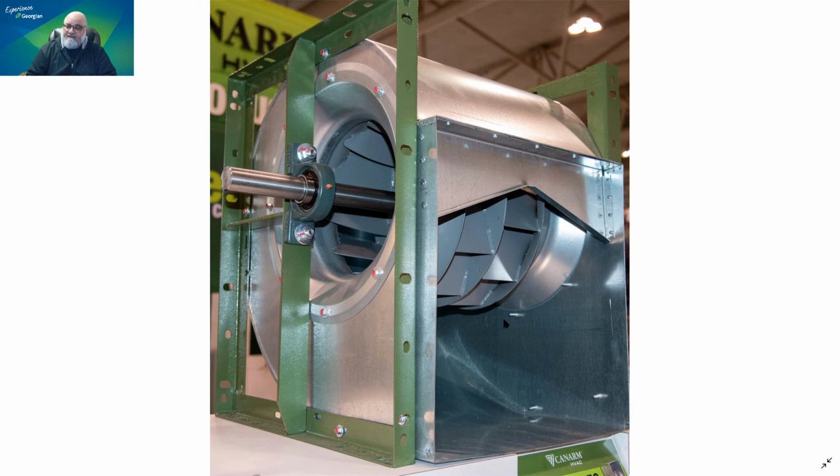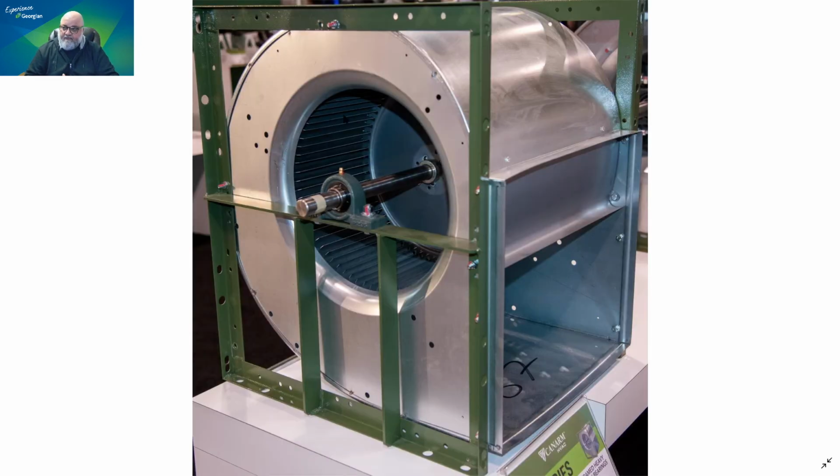Well, because the forward curved and the backward curved have different characteristics. The backward curved is safer for instances of overloading. In the forward curved fan, because of the action of scooping, the more air you supply for it to scoop, the more work it will do. They will just scoop more and more air, basically.